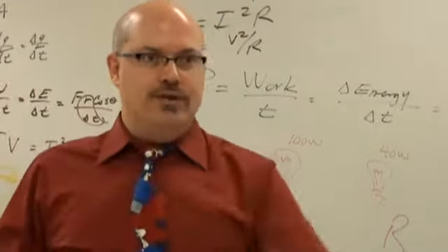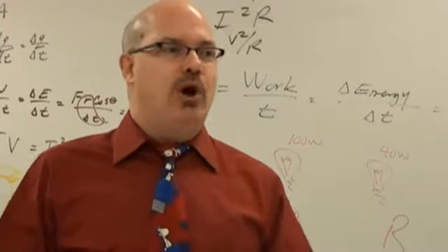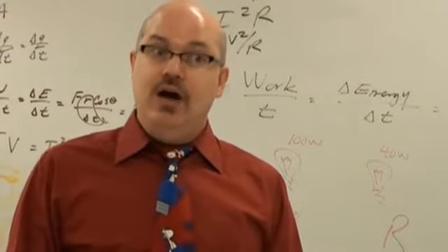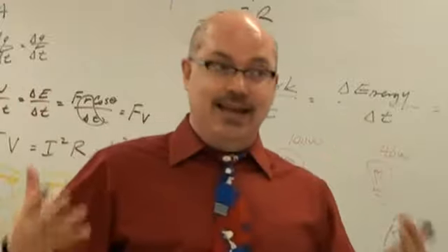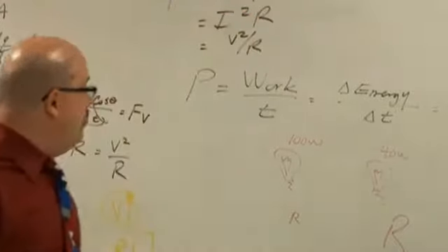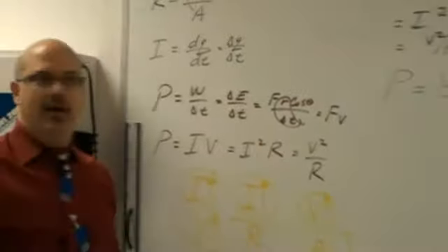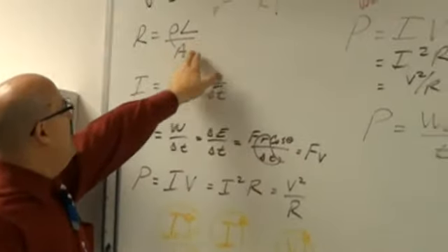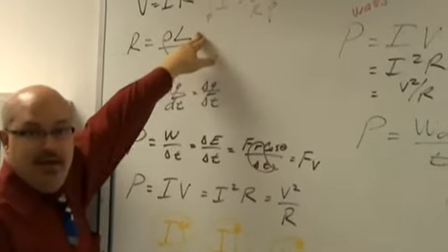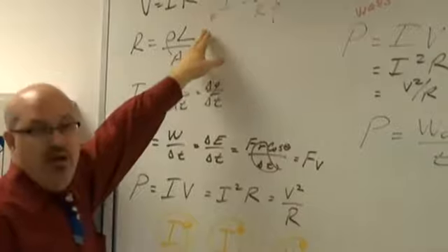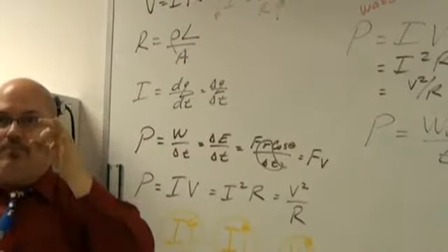And it glows orange. Now, it doesn't glow white hot because you don't want to burn your food, right? But you do want to generate lots and lots of heat, right? And so that filament has very low resistance. It's pretty long, but it's big and fat, right? So therefore, it has a very low resistance and it generates a ton of heat.